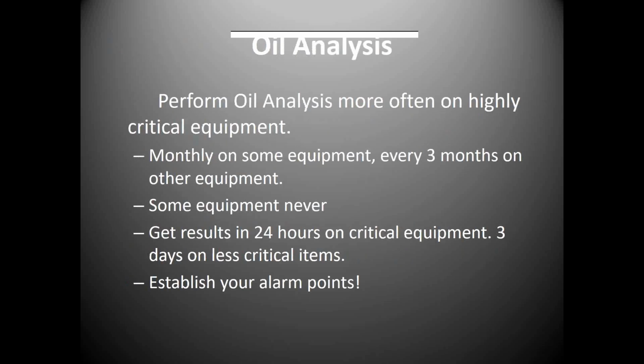Now, how often do we perform oil analysis? Well, we discussed this before. It's sometimes, and at the plant I came from on our critical equipment, our top 10 or 20% of our equipment, we pulled samples every month. On other equipment, we pulled them every 3 months. And like it says here, there's equipment in your facility that you would never do an oil analysis on. But there's things we should do visually. Your operators or maintenance people should still be looking at the oil and its physical condition, maybe putting a couple drops on a piece of filter paper to see what the color change is.